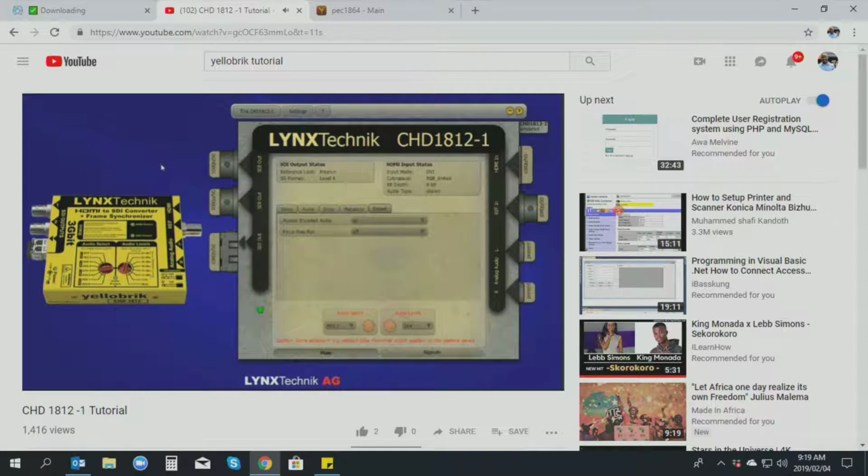Now sometimes people have called me up and said, gee, my module's not working, all I can hear is this digital mush on the audio channels. And the reason for that is because they've got this set to on, and the sending device is sending them AC3. The AC3 is being funneled through the embedder and embedded into the AES output unprocessed. So you're listening to digital noise, which is the encoded audio.